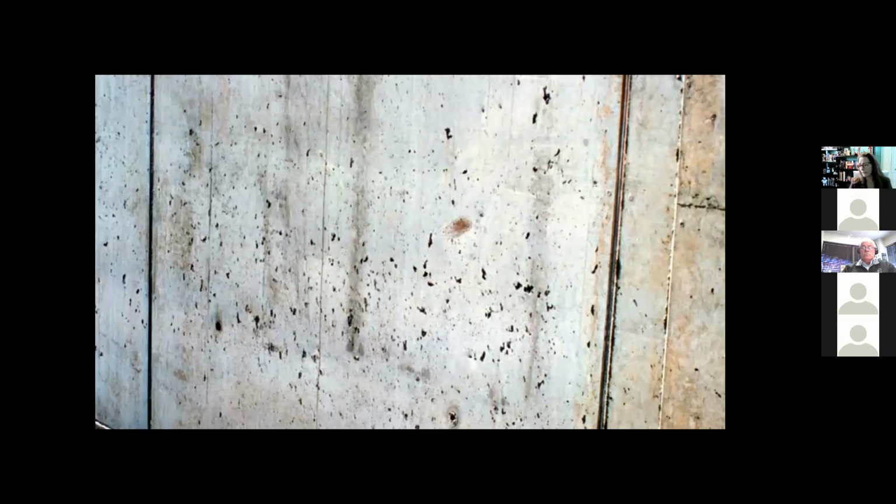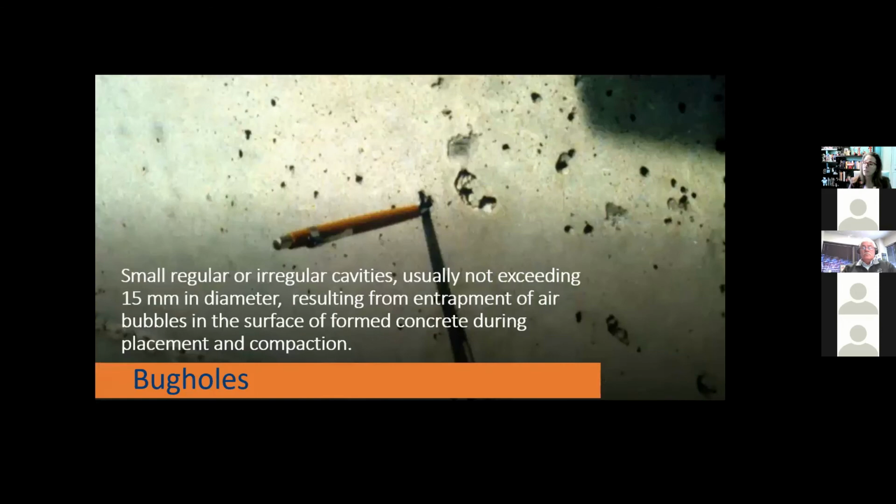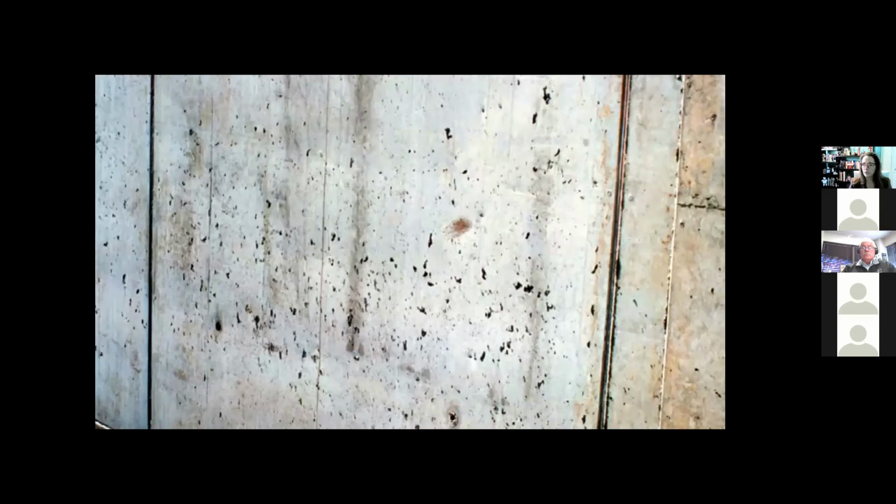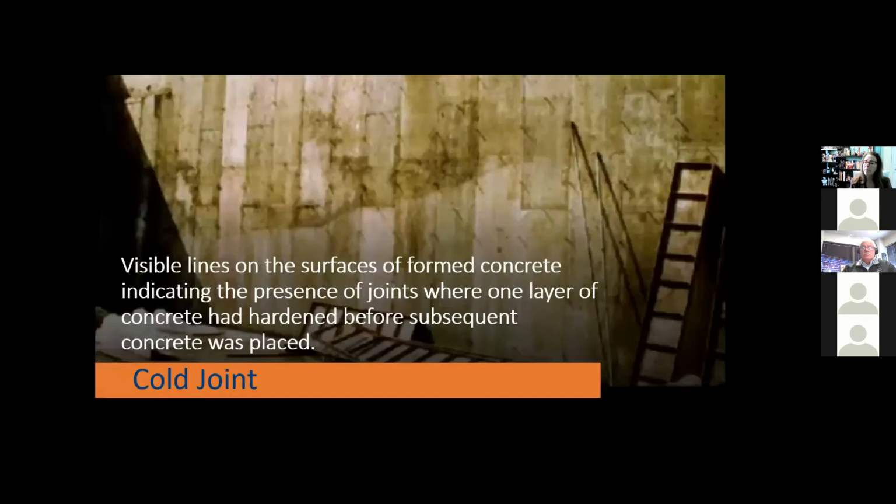Like I said, I'm not necessarily saying this is a beautiful wall, it's a water treatment, but I actually like the look of this. And on a raw exterior hotel, I would not have a problem with that. I'd be more concerned about what their form finish was, if they had any fins, and what they had left for form ties as to how that looks than a bug hole or 2 or 20.